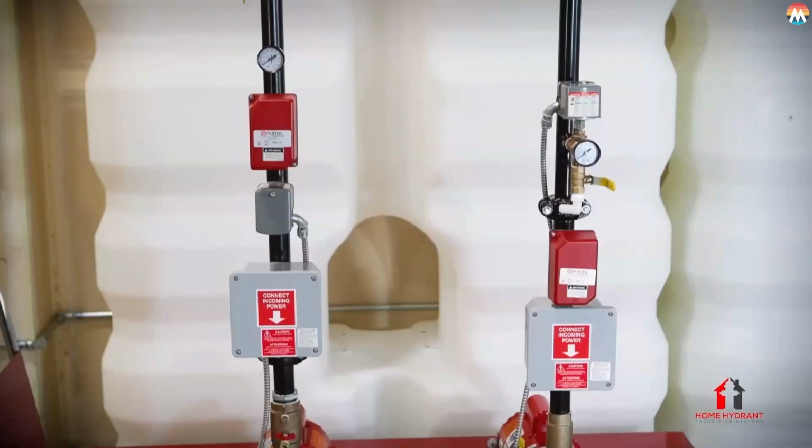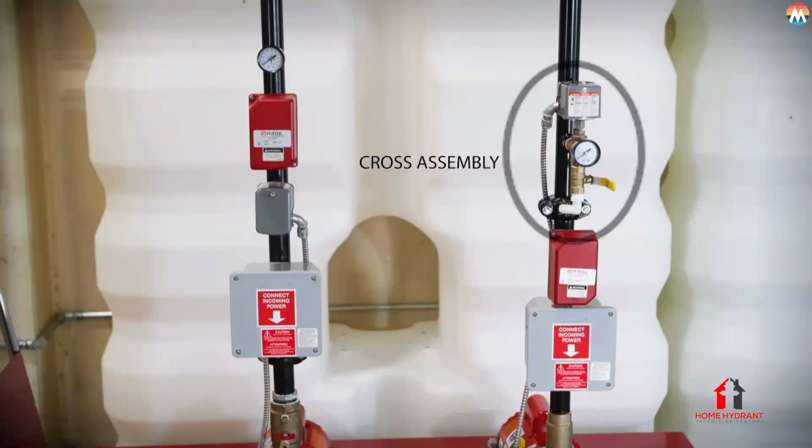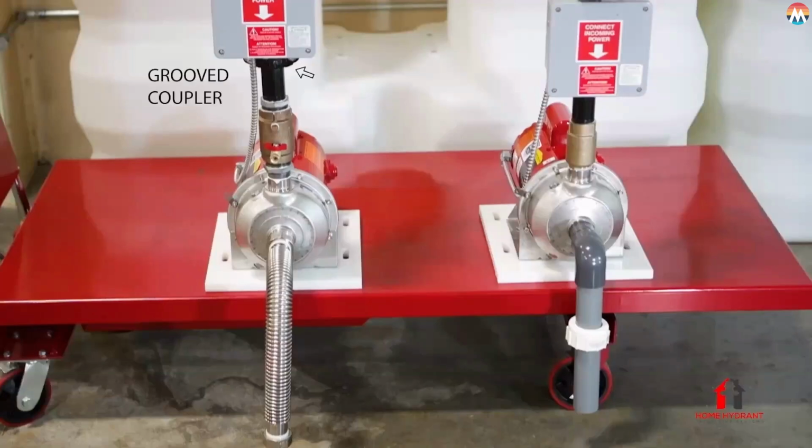We completely redesigned our riser by adding 2 1/4-inch weldlets for the gauge and the pressure switch. This change eliminated the need for the old, bulky brass cross assembly and slimmed down our design. We also relocated the grooved coupling to the bottom of the riser instead of the middle, so that if the pump needs to be removed, the entire riser stays in place.